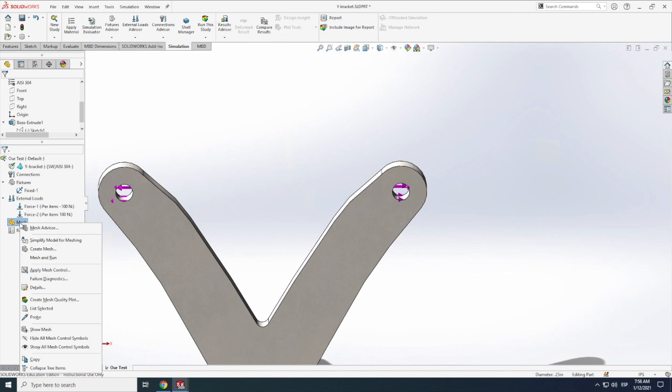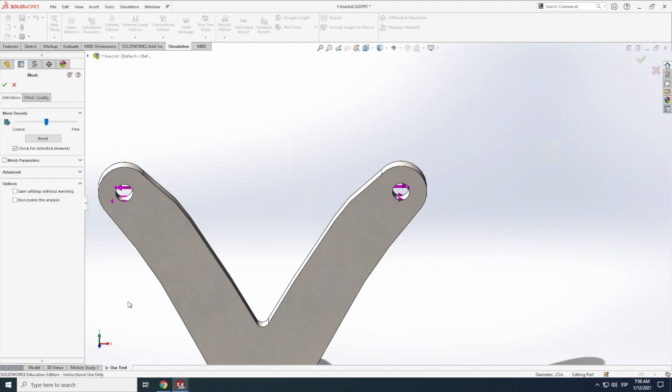So we're going to divide this piece into very, very little pieces in which many different stress and strain calculations will be performed. And as you could expect, the finer this mesh, the more elements that we're going to have, and the more accurate this result is going to be. And here I can just click in here, create mesh. I can say I want it towards the finer side. Let's see what other parameters we have. Oh, we could actually see how big we want the elements to be. I'm just going to use this slider for simplicity.